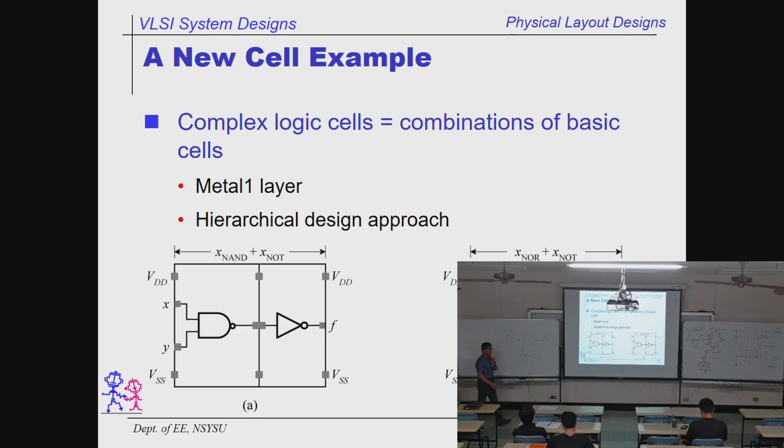All right, and this is how to use this kind of cell concept design. See, this is a NAND gate, and this is the inverter. Let's assume all the layouts are good, after they are verified by the DRC, obviously, and ERC that we talked about. Then all you need to do is just copy them and put them together. And see that we have a short circuit automatically. All the power supplies are shorted, same as the ground. Then you have a layout automatically. I guarantee it works because I worked this way for 30 years. Okay, this is how you do the design.